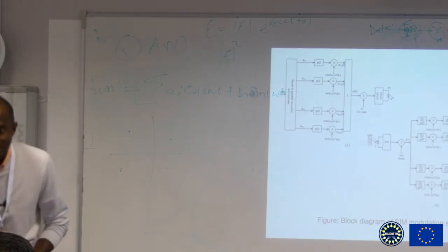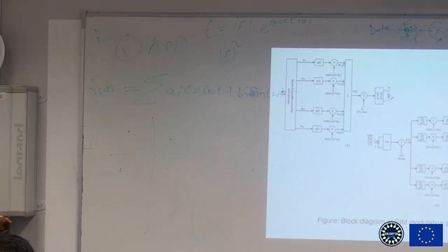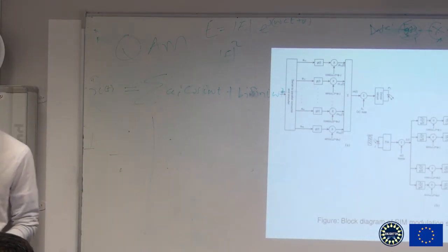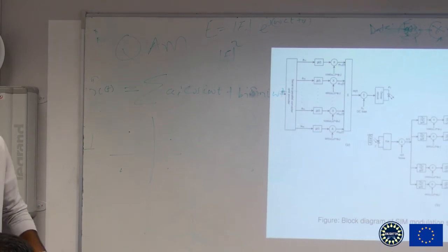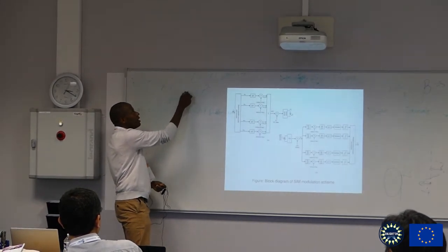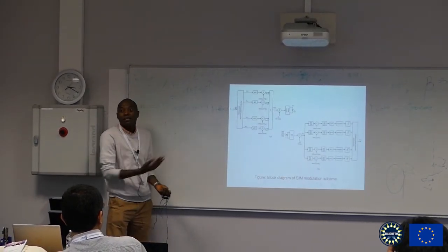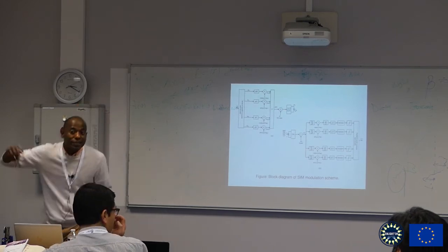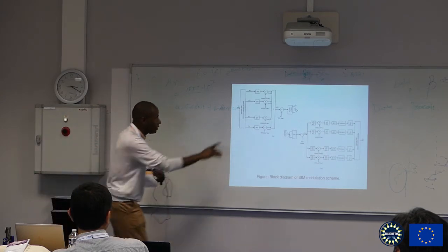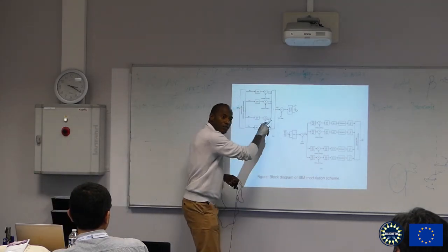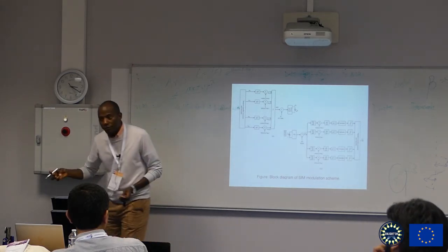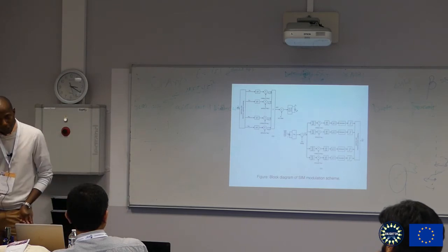Therefore, if I want to implement OFDM, naturally, from Fourier series, these are orthogonal. So if I want to implement OFDM, all I've got to do is carry out FFT and IFFT. Because I'm starting from here and going back this way, I have to do IFFT with my constellation symbols. That's all. That's the only difference because we do it in the digital domain. All right? Because they are all the same. Conceptually, SIM, CAP, and OFDM are exactly the same thing with these little differences. Therefore, all of them have the same spectral efficiency.